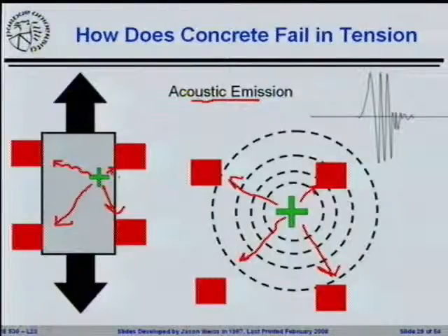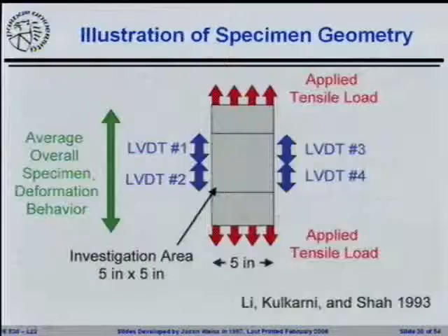It's sort of like a high school math problem. You know, the train left going 20 miles an hour in this direction, 60 miles an hour in this direction. Where did it leave from if it got to Chicago at 3 o'clock and got to Memphis at 6 o'clock? Same type of problem here. Something happened. A crack was formed inside of the material. You know what time the wave was picked up at the different sensors. You can back calculate where it started.